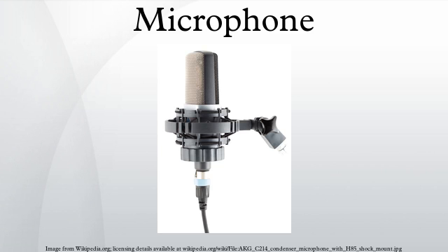Crystal microphones were once commonly supplied with vacuum tube equipment, such as domestic tape recorders. Their high output impedance matched the high input impedance of the vacuum tube input stage well. They were difficult to match to early transistor equipment, and were quickly supplanted by dynamic microphones for a time, and later small Electret condenser devices. The high impedance of the crystal microphone made it very susceptible to handling noise, both from the microphone itself and from the connecting cable.